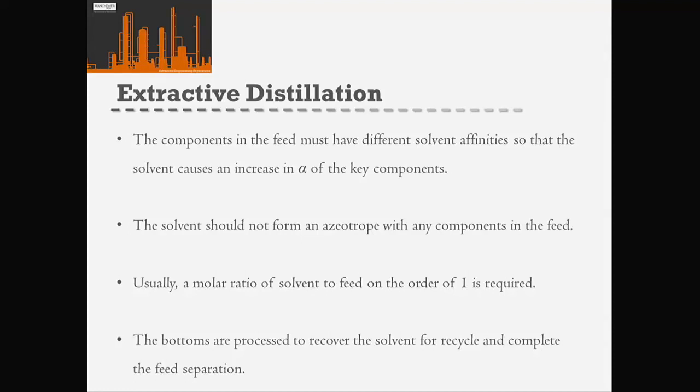The reason for this is that if you need to start increasing the pressure a lot, maybe 10 times the pressure, 20, 100 times the pressure between the columns, it then becomes far too expensive to be actually a viable technique. And if the composition of the azeotrope doesn't move very much, then the difference between the feed into the second column and what you're returning into the first column isn't a lot, because essentially it's just the difference between the two azeotrope compositions.